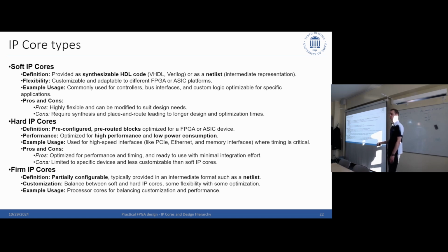Very often, when you get into very big blocks like processors, you might want one core, a different memory type, different interfaces, a different cache size, because on the FPGA you will have something in between where the rough architecture is like a hard core, but additional cores or any optimizations you can maybe customize.